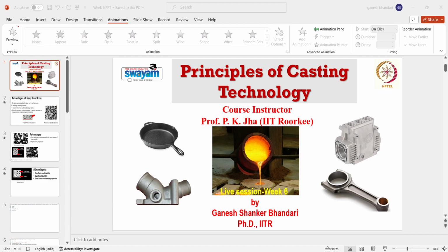We pour that molten metal into the copper mold at a temperature of around 1600 to 1700 degrees Celsius. But what we generally do with these copper molds is provide a continuously flowing water jacket, which cools the copper mold so it does not melt down.